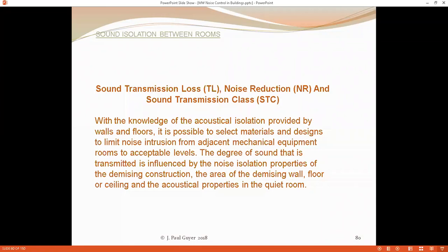Another, of course, as you've probably encountered this already in your careers, another good way to improve the sound reducing characteristics of a wall is putting fiberglass bats, acoustic bats in the airspace between the studs in a wall. That is because a certain amount of the acoustic energy passes through the airspace between the studs in the stud wall.